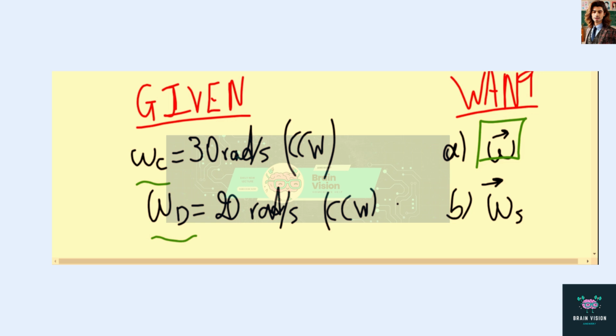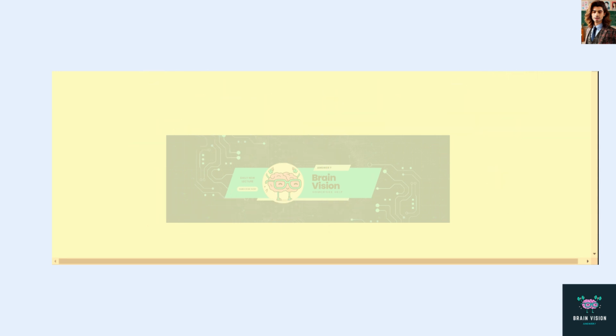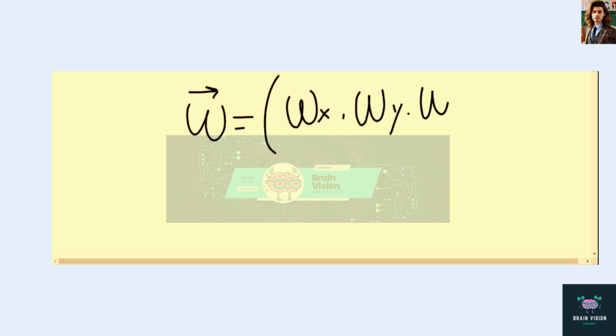Actually, the whole derivation of the solution is quite long, and I might have to skip some parts. But anyway, let's begin. The first thing to make clear is that for gears A and B, there's both a common rotation about the inclined shaft FBA and a common rotation about the shaft FH. It's not only that they rotate about the inclined shaft FBA. The calculations would have been easier if the rotation was only about the inclined shaft.